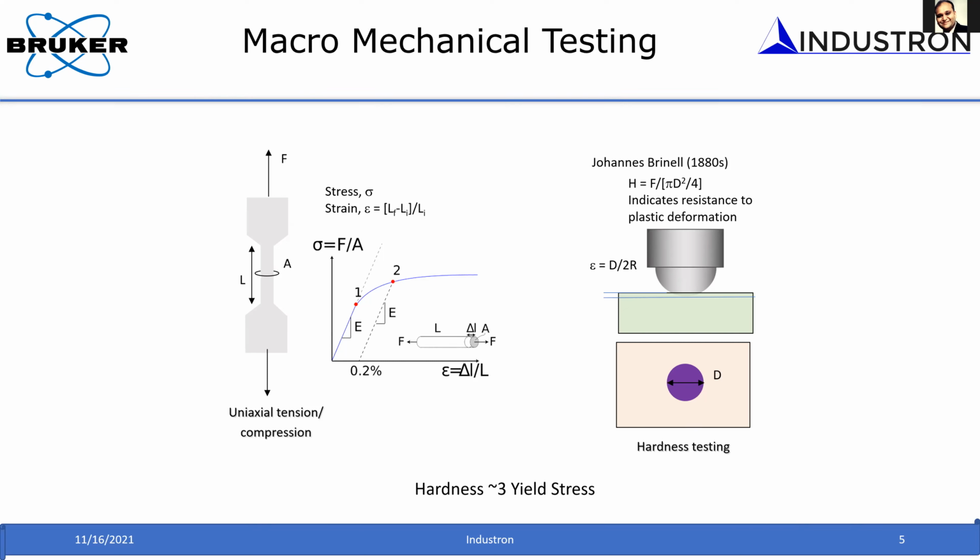The state of stress under indentation is much more complex than in a uniaxial tensile test. When you do indentation experiments, you apply a complex stress state, for example, 2/3 hydrostatic and 1/3 shear. So it's a complex stress state, but it is still more local, and it gives you the information that you want to know about the plasticity of the material much faster. That is the reason why you do this hardness testing.